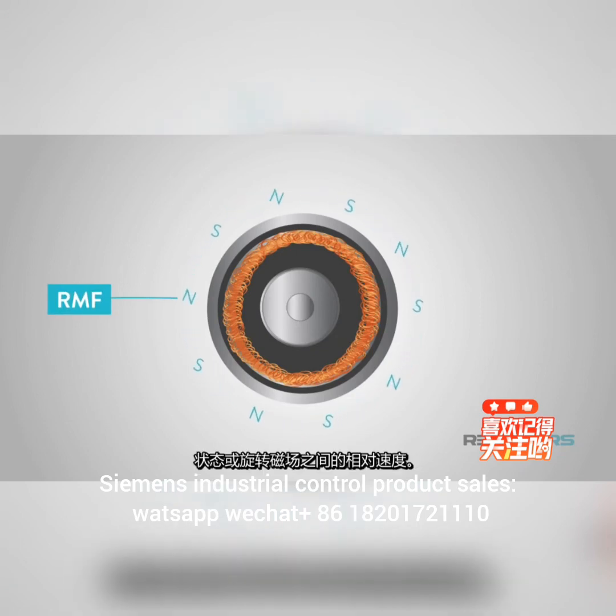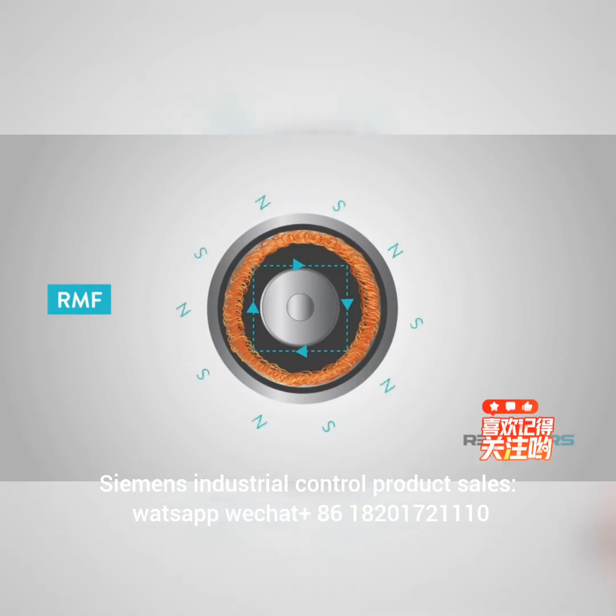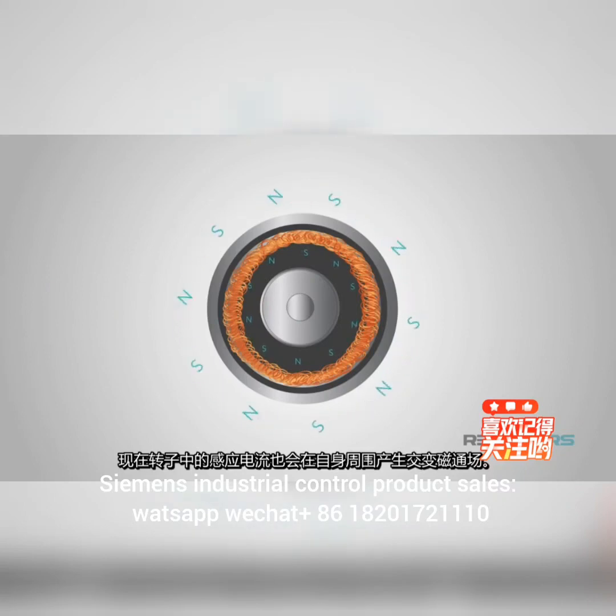The relative speed between stator rotating magnetic field and rotor conductors causes an induced electromagnetic force in the rotor conductors according to Faraday's law of electromagnetic induction. This is the same action that occurs in transformers. Now, the induced current in the rotor will also produce an alternating flux field around itself.